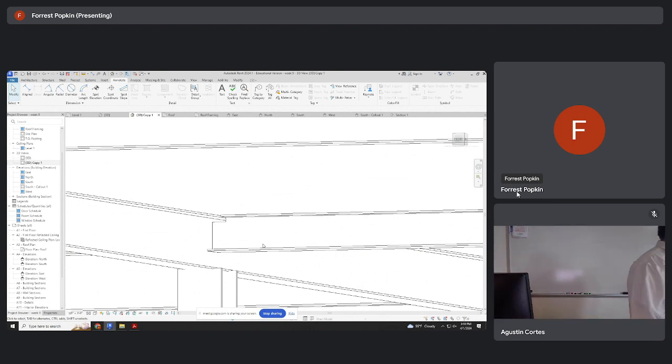It might happen in really crazy situations where you have a really, really small run and they're like, well, in order to do that, it's a custom cut or something. So anyway, in your particular models, since you have the floor-to-floor set, you'd want your building to follow that. And that means that you're probably going to have to go back into your parameters and modify the offsets. Okay, and that's for the decking part, just to make sure it doesn't interfere with the finish. Correct. So in your instance where you already have floor-to-floor heights and everything done, you'd probably just want to come in and then shift out whatever floor you have to make sure it's actually legit.